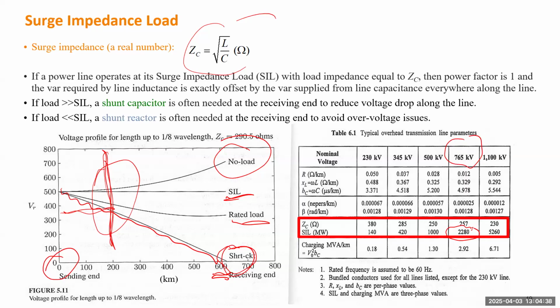First of all, when you add a transformer, it doesn't change the transmission line, which means whatever that transmission line has is still there. But voltage can be controlled by a transformer because you have a tap changer. If you move up, voltage on that side will be increased. The secondary side, if you move down, it will decrease.